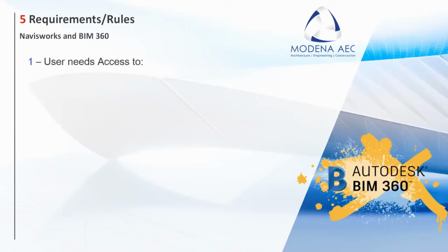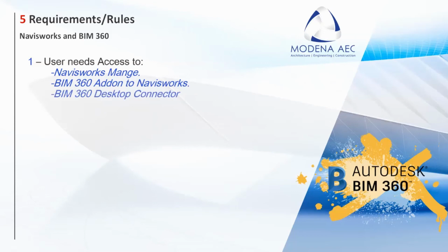Number 1, users need access to Navisworks Manage. Remember, Navisworks Manage is the platform where you are running your clash detection. If you are running Freedom or Simulate, you will not be able to run this particular relationship. Again, under number 1, you would need the BIM 360 add-on to Navisworks. By the way, this add-on is absolutely free so long as you own your Navisworks license or are subscribed. And then, of course, you need the BIM 360 desktop connector. The desktop connector is free to use and requires the same sign-in as your BIM 360 account.